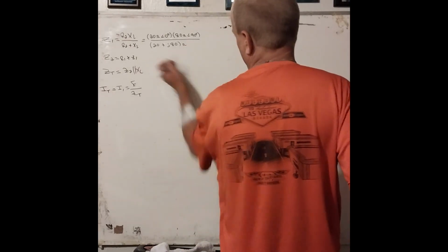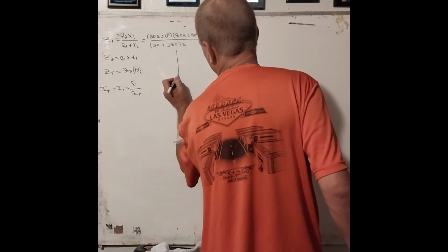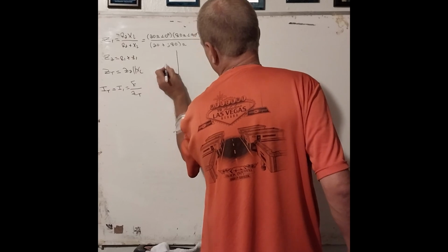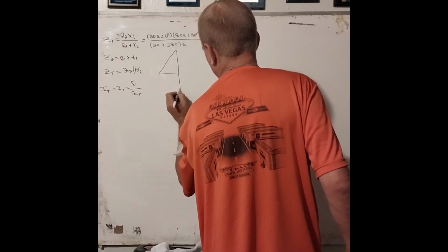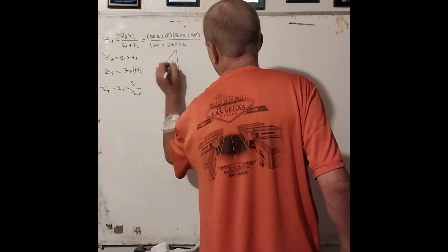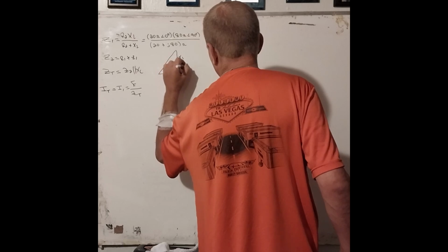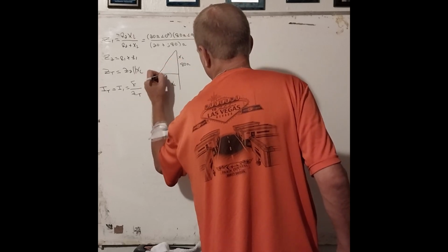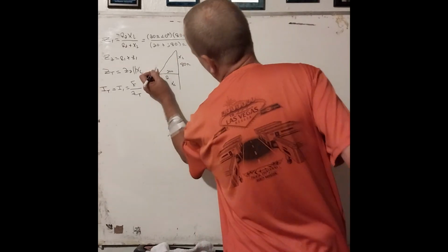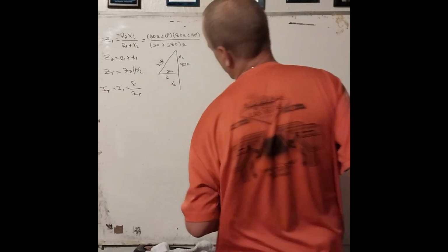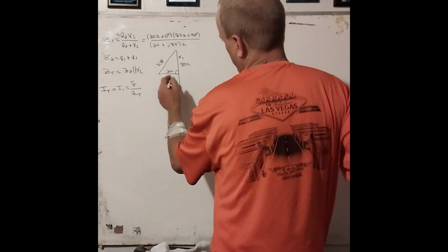But this requires the Pythagorean theorem, because when you plot these values on a graph, here's your x sub c, here is your x sub l, which is going to be J 80 ohms. This is x, this is r, and so this is 20 ohms. We're looking for the magnitude of the hypotenuse.